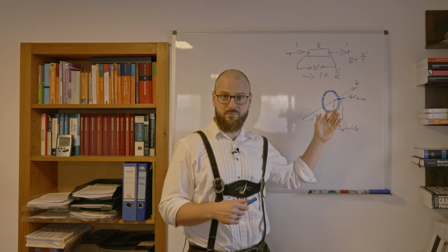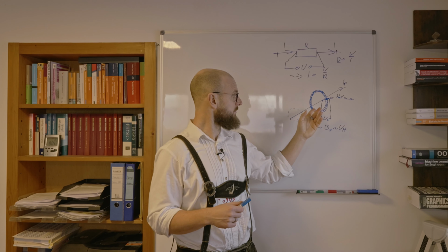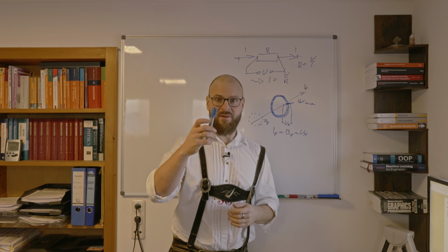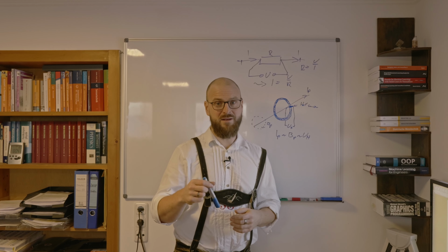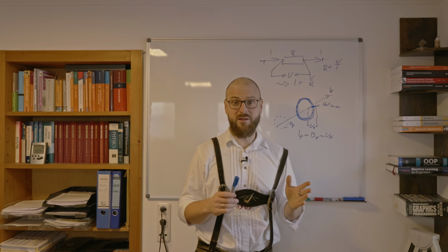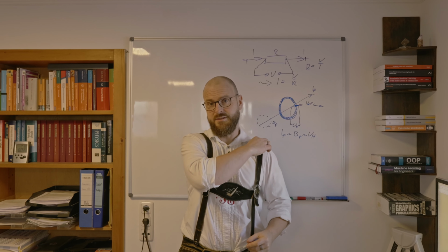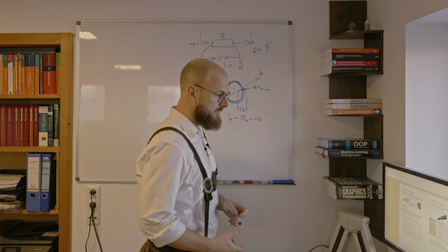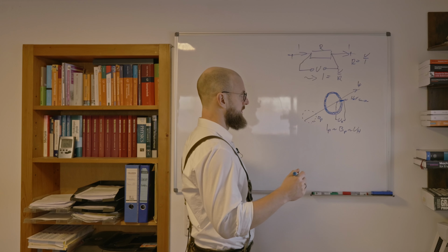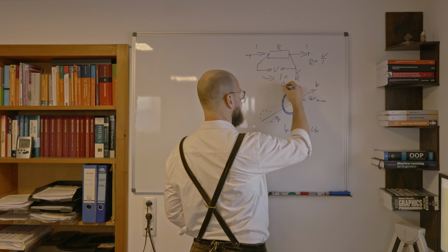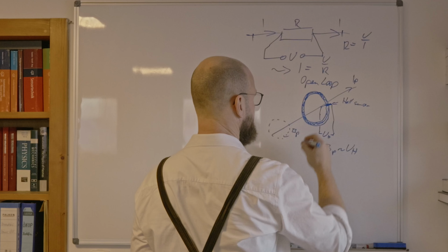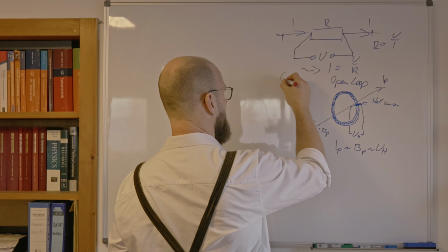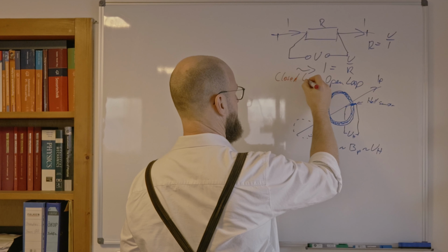I already mentioned the second problem about this, the hysteresis, which means when the current rises and then falls again, the measured values for the magnetic field will be different. We have to deal with that hysteresis. That gives us some problems, and that is the reason for the improvement of this measurement type, which is called open loop, which now can be improved in a closed loop way.